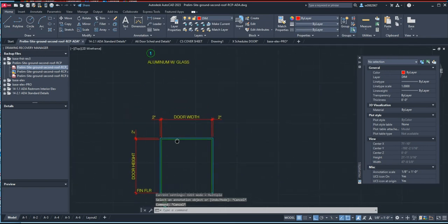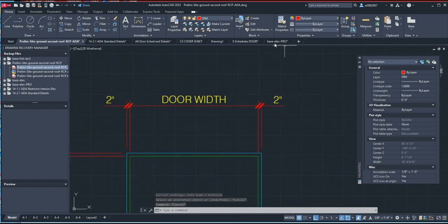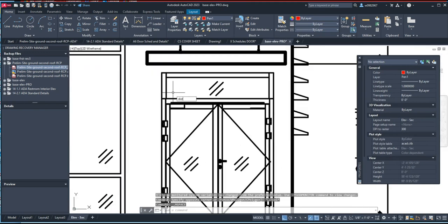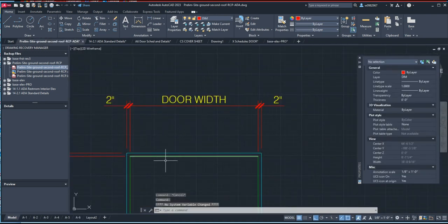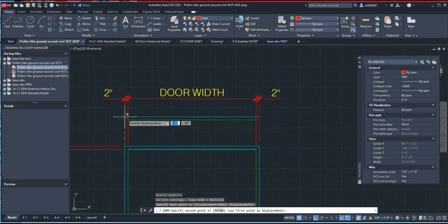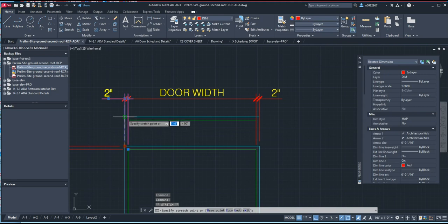Okay, and then we have a transom. And what is the root of this transom? So click distance from here to here is about 1 foot 6, 18 inches. So over here, we go back here, and I'm going to offset 18 inches, and then copy the frame width, and then simply bring this point up here, bring this point up here.